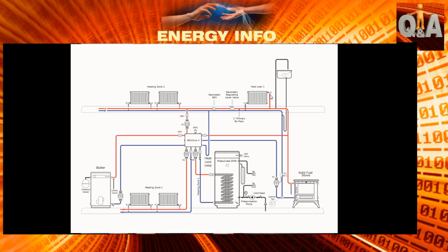So with that scenario, you can have a pumped zone upstairs that also heats the heat leak, and you can have a heat leak that won't heat the radiators upstairs until the zones decide to call. So that could be one radiator or 2 radiators, 3 radiators, whatever. The more the better, really, to dissipate the heat from the boiler. So that would calculate how many rads you want, or the size of the radiator.